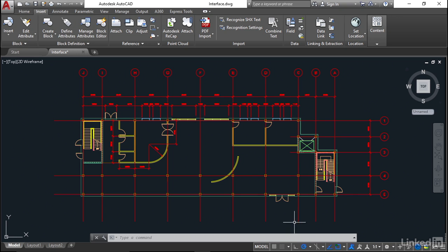It's all these little icons down here. So you'll notice you've got things like grid mode, snap mode, and as you come across, you've got ortho mode, you've got polar tracking. Some of the more important ones are things like object snap tracking, object snaps, and so on. Now, those are all displayed on your AutoCAD screen, and they're known as your drafting settings. So things like your object snaps are always going to be on so that you can snap accurately to the objects in your AutoCAD drawings.